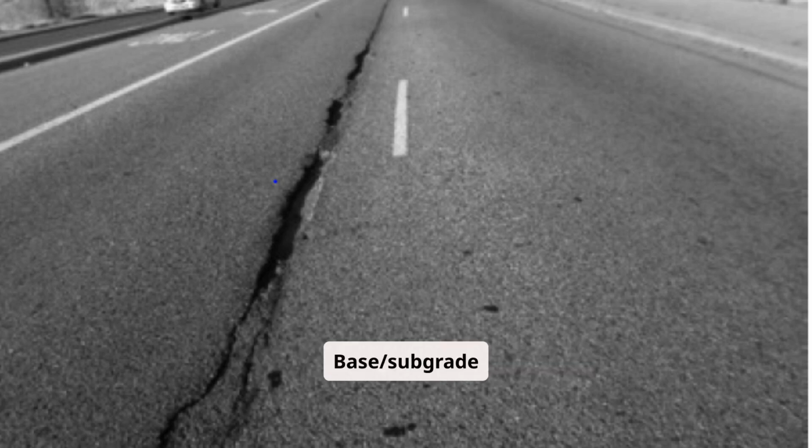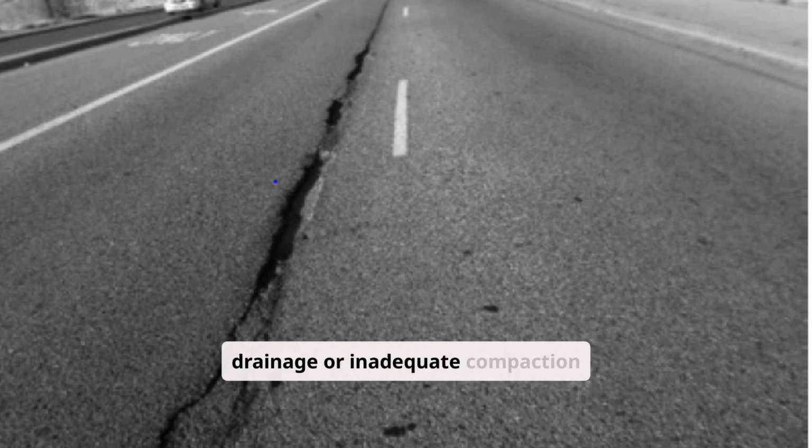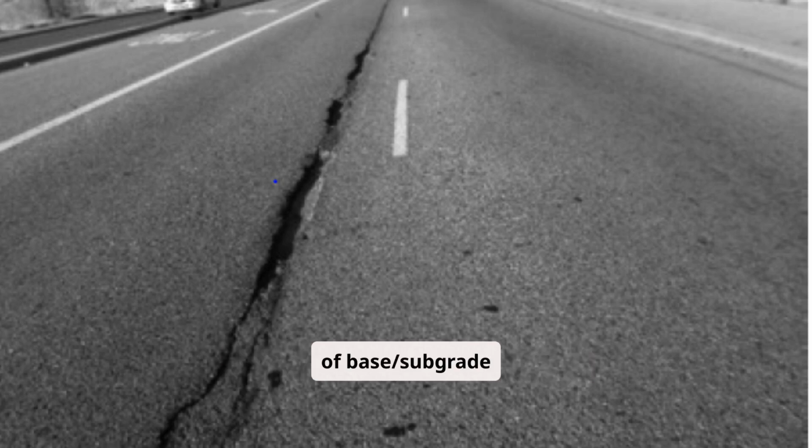Base subgrade problems. Poor drainage or inadequate compaction of base subgrade causes some major cracks, as discussed earlier. Some other forms of distresses, such as swells, bumps, and sags, also occur due to base subgrade problems.